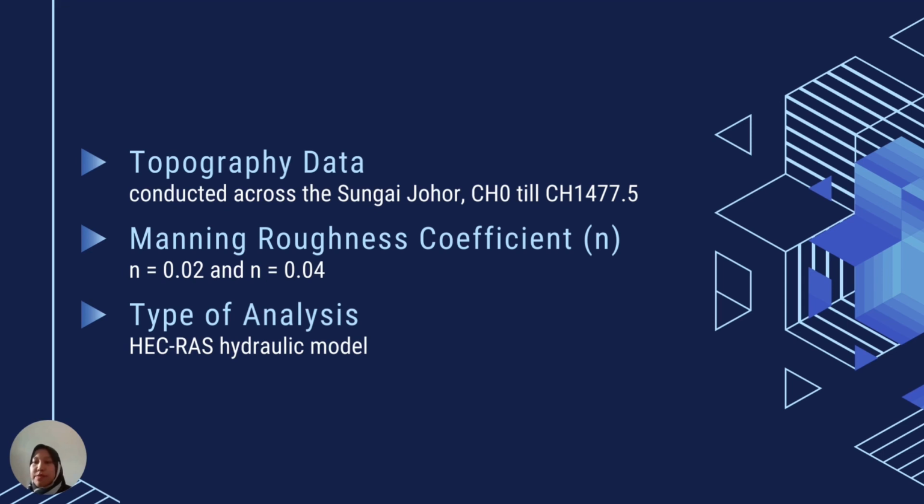to calculate the surface profiles of water under various flow circumstances. It is capable of simulating subcritical, supercritical and mixed flow regimes for streams made up of an entire network of channels. It also helps to determine the water surface layers that correspond to floods with varying return periods of 10, 50 and 100 years, implying the need for increasing embankment height or strengthening channel sections under different flooding situations.